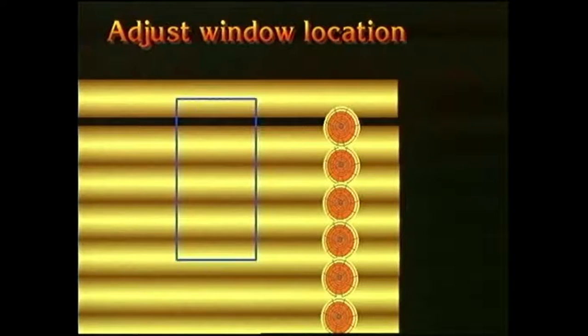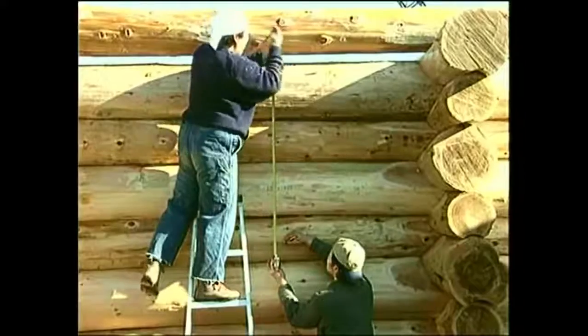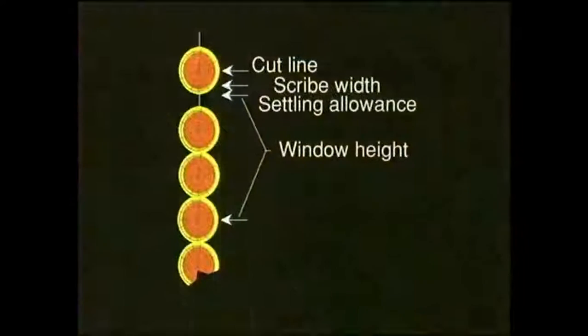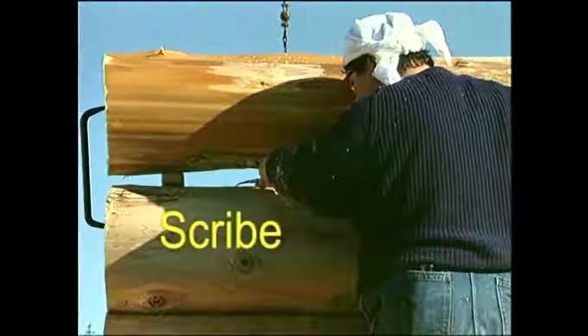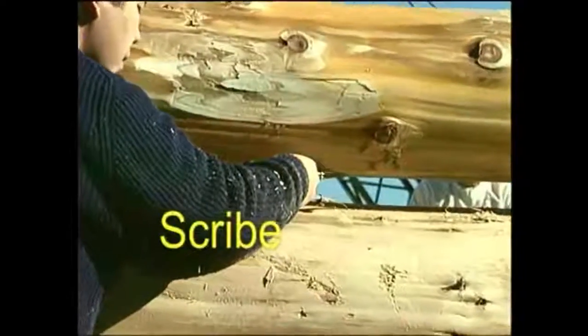Settling allowance is related to the height of the opening you are working on. For green logs, this allowance should be 1 to 16, or simply divide the door or window height in millimeters or inches by 16 to give you the additional height needed for settling. For example, for a window that is 900 millimeters or 36 inches high, the allowance would be 900 divided by 16, which would be 56 millimeters, or 36 divided by 16, which would be 2¼ inches.